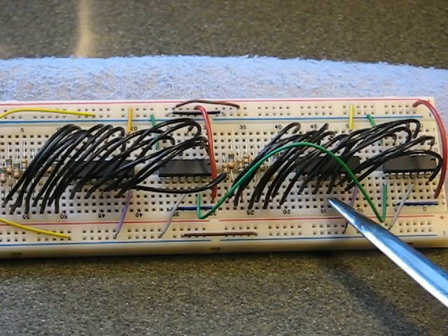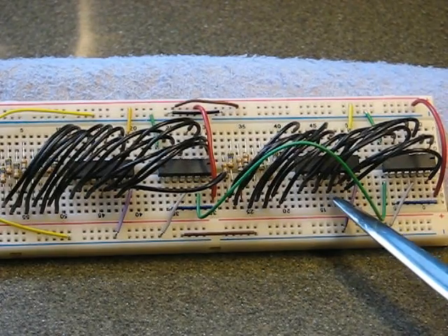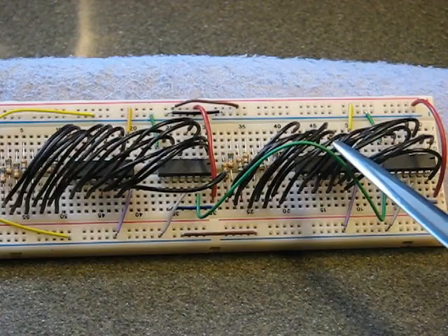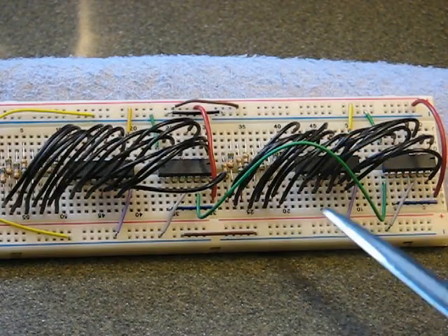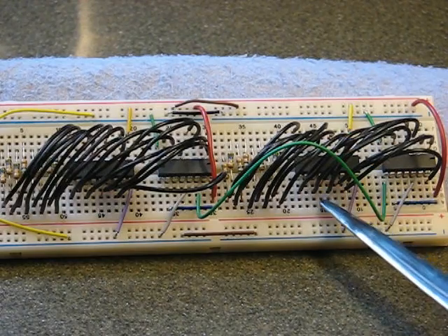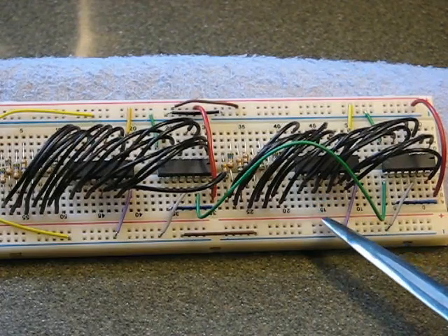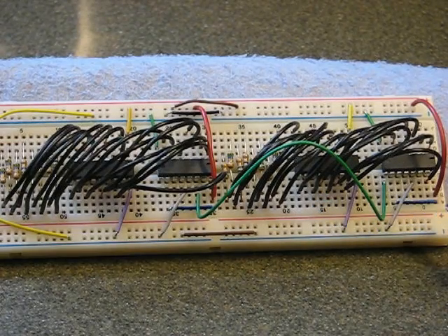The transistor array takes the power from the computer power supply, and this chip switches the power on and off to each of the 8 LEDs that are connected to this chip. So there will be 8 wires from here to the cabinet for 8 LEDs. Now the way shift registers work, I can stack them together.